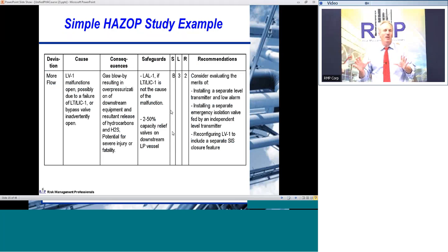So that HAZOP is transforming an operational view of the world into a what can go wrong view of the world. But with that different perspective, that's really the magic, and it's the tool you need to provide that perspective for identifying if there are design weaknesses. And not only from a safety perspective. When you're going through and identifying design weaknesses, there's a huge overlap between the kind of weaknesses that represent a potential safety impact and the kind of weaknesses that represent a potential significant operational concern.